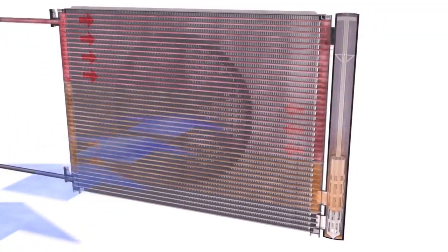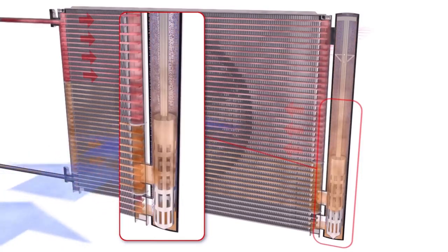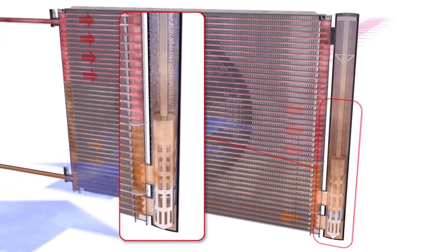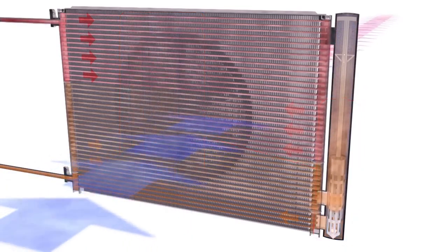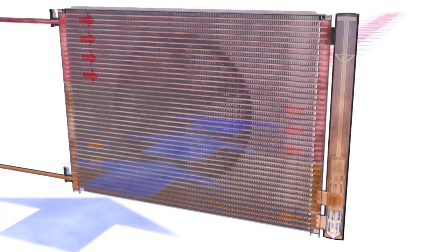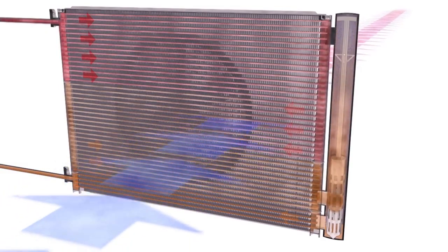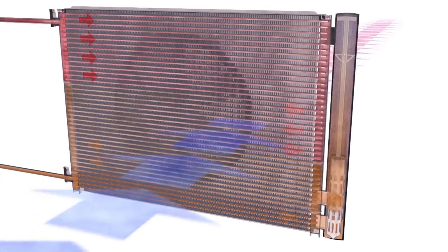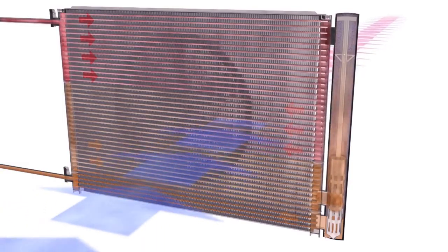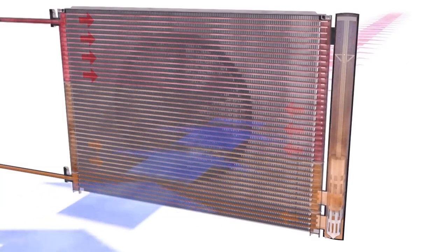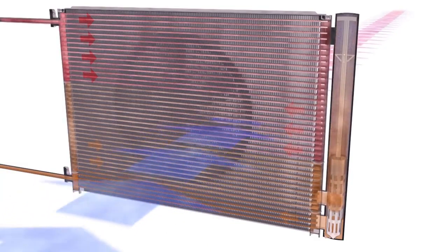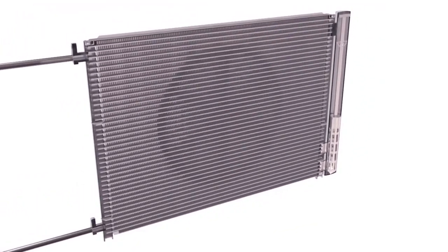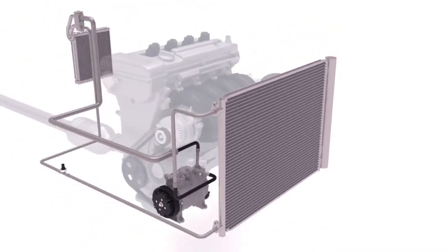This loss of heat reduces the gas temperature, which allows the gas to condense within the condensing section, where it naturally changes state to a liquid. The liquid refrigerant then passes to the gas-liquid separator section, where any remaining gas is separated from the liquid, providing further opportunity for the gas to release heat and change to a liquid. The liquid refrigerant then receives additional cooling in the subcooling section, where the heat energy contained in the liquid refrigerant is again released through the condenser fins to the air. This further reduces the temperature and improves the overall cooling performance.